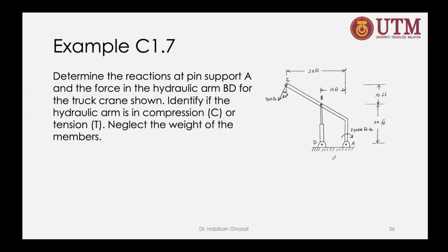There is an applied force of 900 pounds on the hook, and also a concentrated moment at point A given to you. You are required to find the reaction at the pin support A of the truck, and also at the hydraulic arm. You also need to identify whether the hydraulic arm is in compression or in tension.